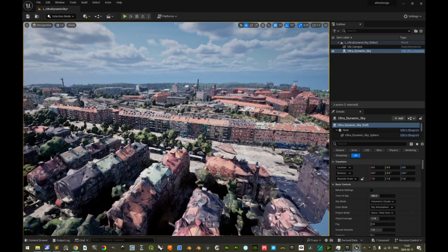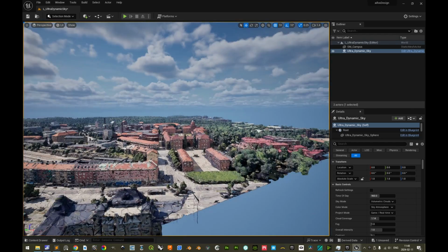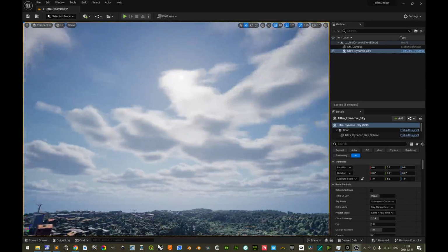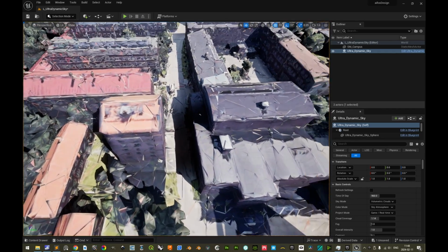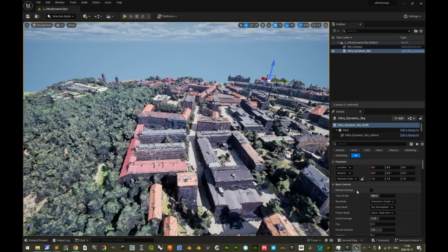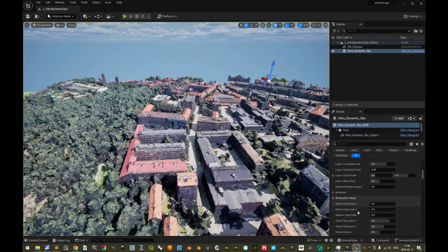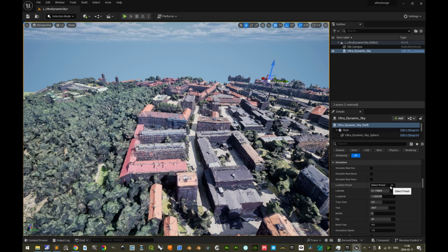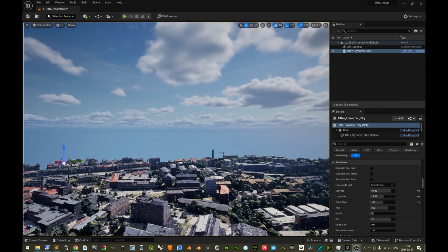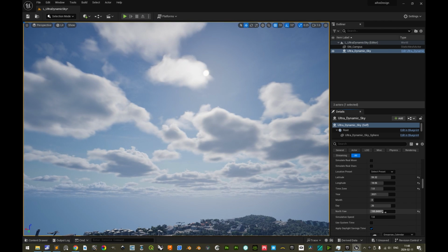Exactly, very good. Regarding the north orientation here, we are gonna overlook this. We can just position the sun so that it is co-aligned to the shadows of the imported texture here. So we'll go down here in the settings and make sure that we select Stockholm as our coordinates. Let's make sure that we find this first. Here, very good. Location preset should be Stockholm. Like that. And then we can adjust the north yaw here.